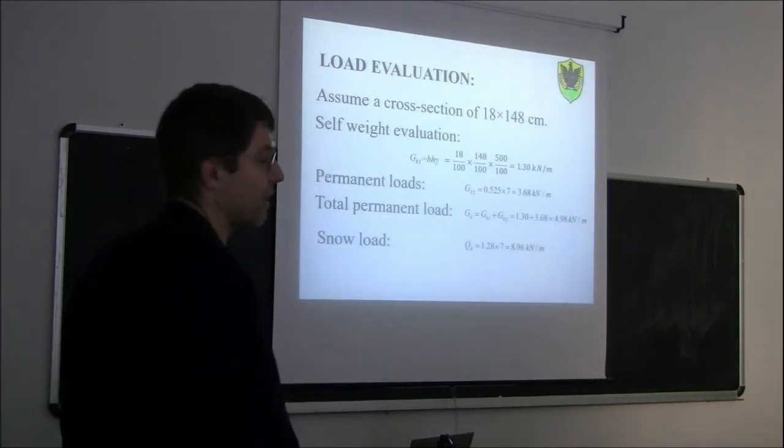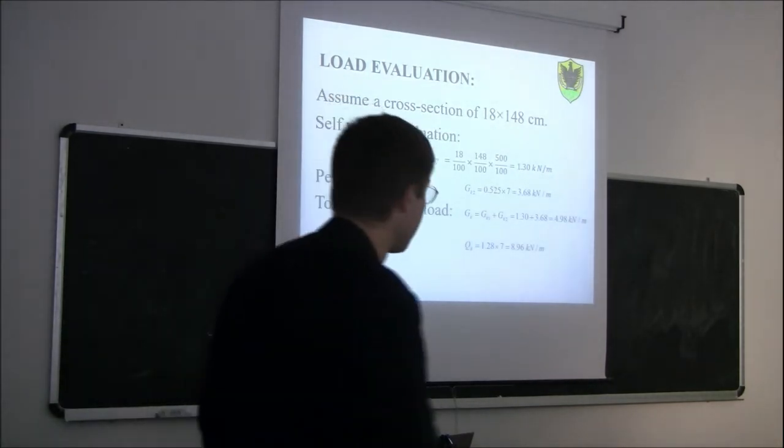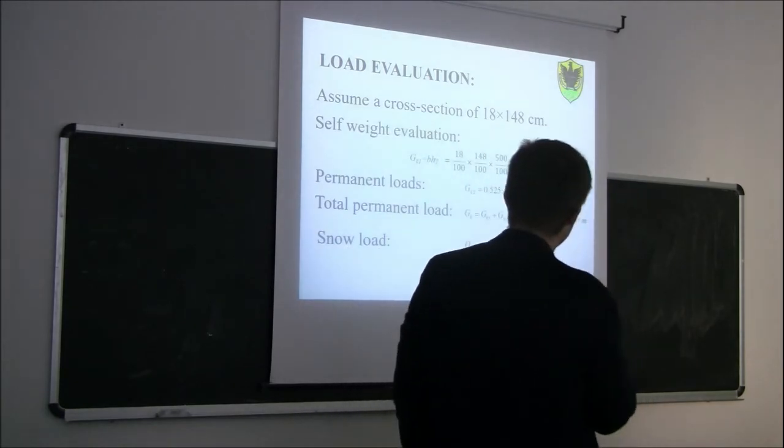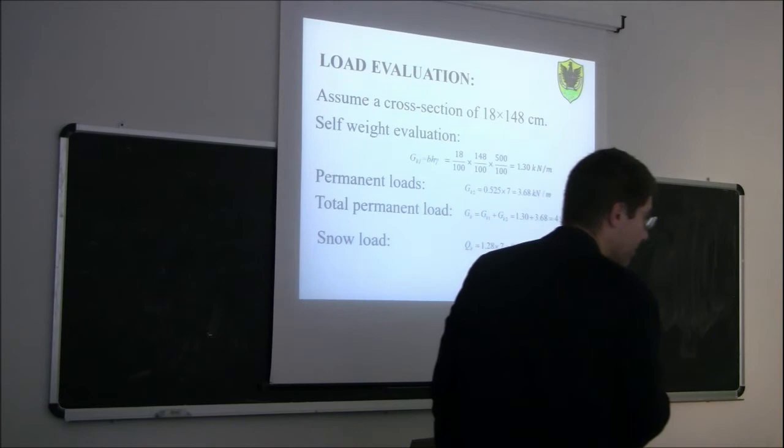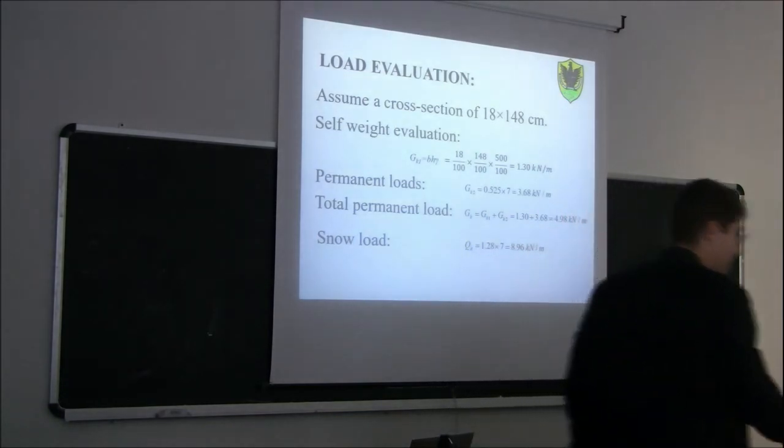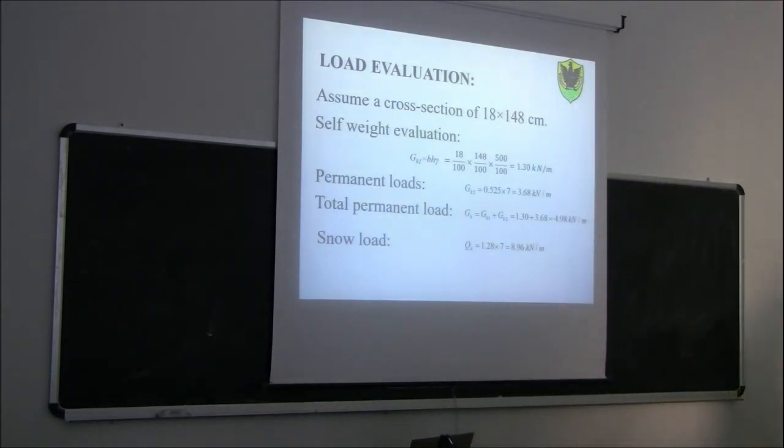Of course, another remark we could make is that if you get here a wrong value of the self-weight, it's not as important as if you get a wrong calculation of the self-weight for reinforced concrete. For reinforced concrete, the self-weight is a much higher percentage of the whole ultimate load. Here it's less.